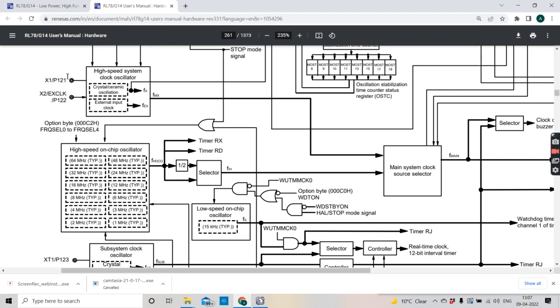This video is related to the programming, so let's stick to it. You can place external oscillators on these two pins. Or if you have an external oscillator giving you a clock signal, you can place it on the X2 pin.